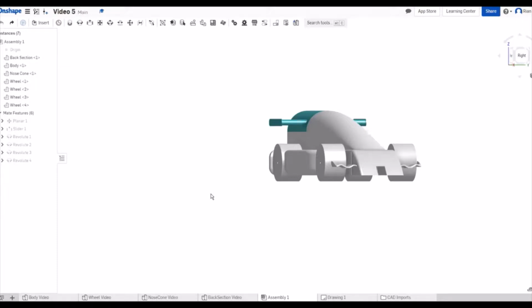Then conversely, it is a source of turbulent air and also a source of drag around that sharp corner, which could be filleted, but this is just a demo car. There is turbulent air at the back, and there's also drag at the front, which is not ideal, but I would prefer to have it overall than not have it.